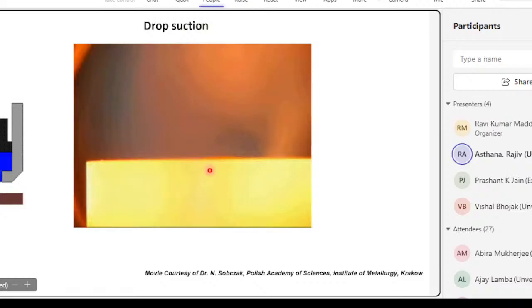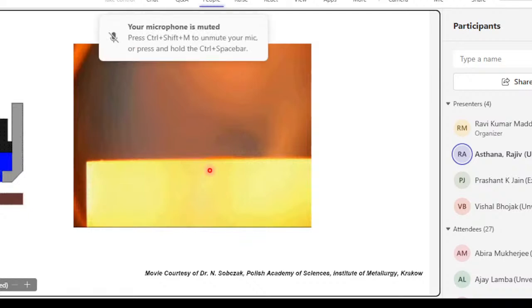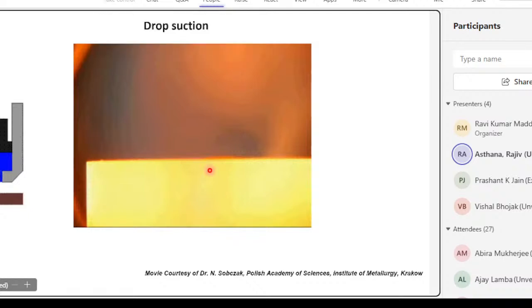Some of this may not be of direct interest to people here, but these are the kind of experiments one does. Now here you're looking at 4 different quartz plates over which we placed solid aluminum and then melted it. You can see how the aluminum is moving through these quartz plates under high vacuum at high temperatures. And when the cooling has taken place, you can see the quench cracks. From these kinds of experiments, we are able to calculate the rate of interaction between liquid and solid. These could be of use in melting processes and making composites of aluminum with ceramic materials.